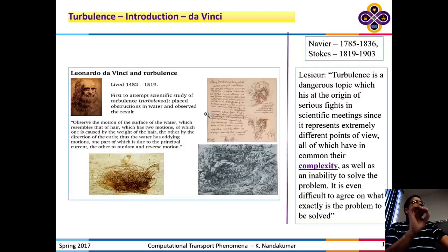And that turbulent flow evolves through instabilities in the flow. Particularly, you need a mechanism to generate this shear instability at the wall. So if the wall is not moving, if the fluid is moving, you have a boundary layer, and that creates a vorticity, a rotation near the wall. And that diffuses and spreads its energy to larger and larger scales. So this is the idea behind what turbulent flow is.